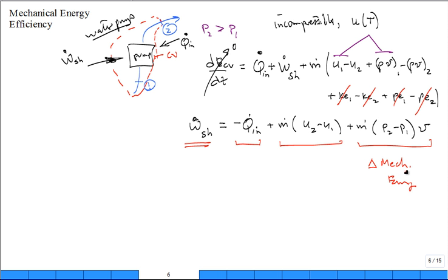It's a boost, it's the flow work component, the PV term, okay? Flow work, mechanical energy. Not boosting the internal energy or heating up, or heat transfer to the surroundings. Now, you ask yourself, what did you really want? Well, we wanted it to go into this increase in the mechanical energy of the flowing fluid.